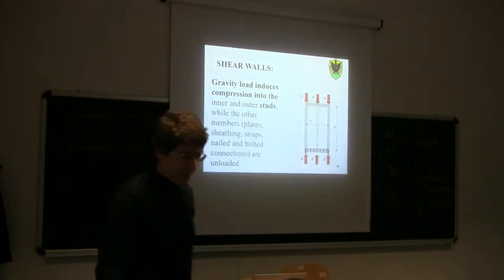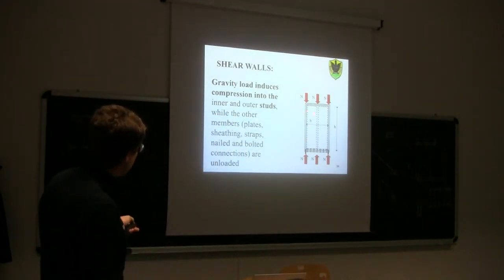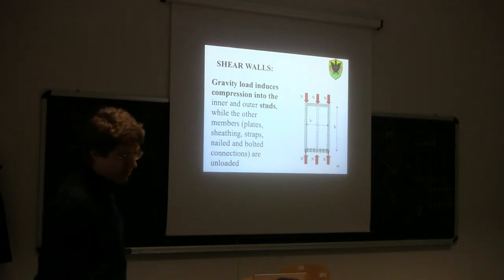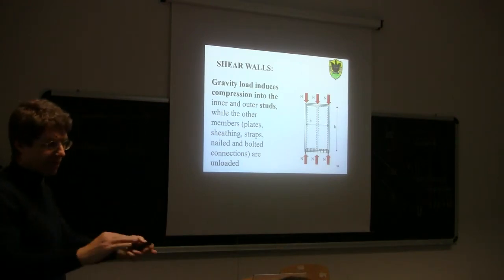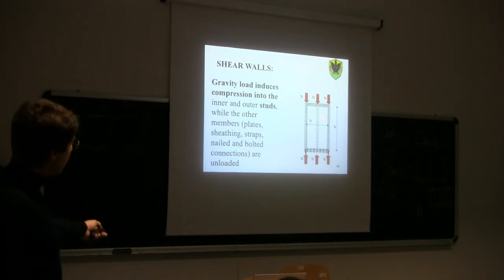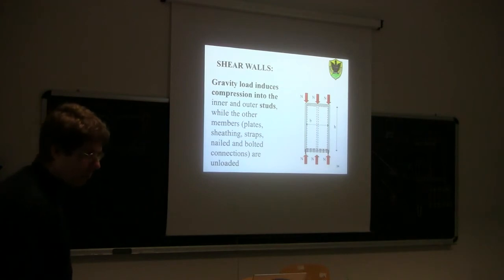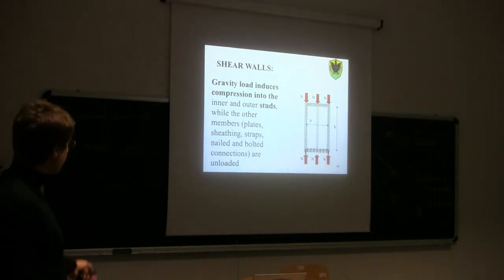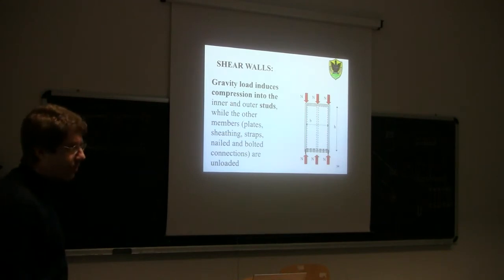So? The studs for sure. What else? Only the studs, nothing more? During the construction. No, after. Let's say after everything, after the construction is finished. So the studs will be stressed for compression, parallel or perpendicular to the grain? Parallel to the grain. And what kind of verification do we need to do for compression parallel to the grain?